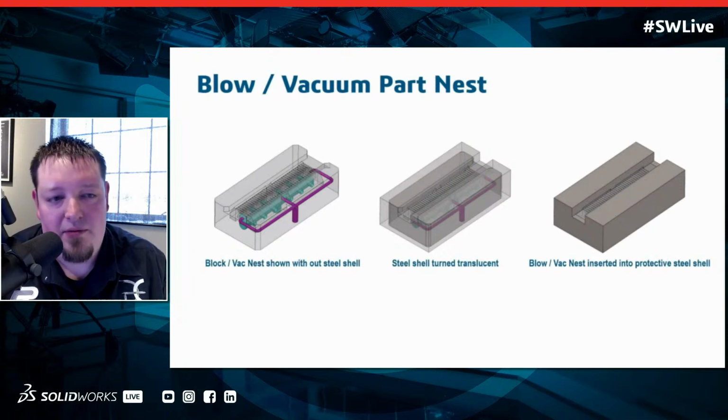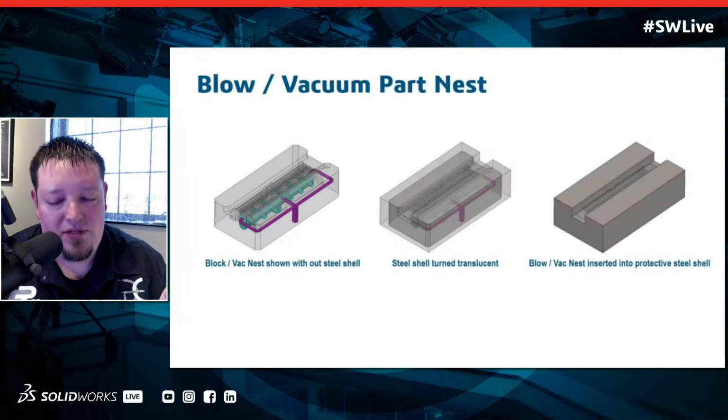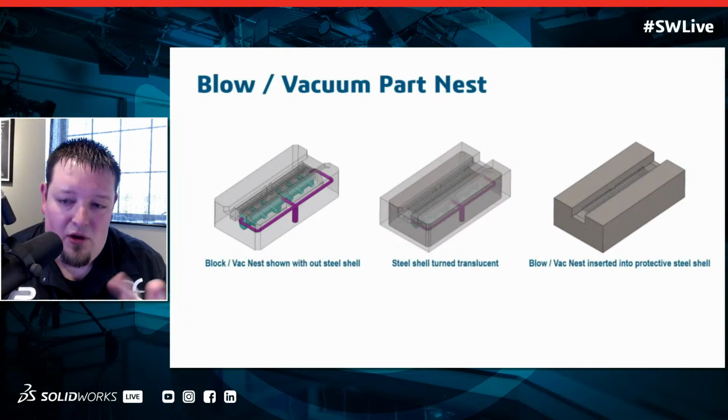And it was really important for them to be able to see inside of the part, which means it needs to be clear. Well, we have a really good, high quality, clear SLA resin. It's called Somos Watershed, and so that material was clear. The SLA gives us the fine feature detail to do all the holes we'll see here in a second.